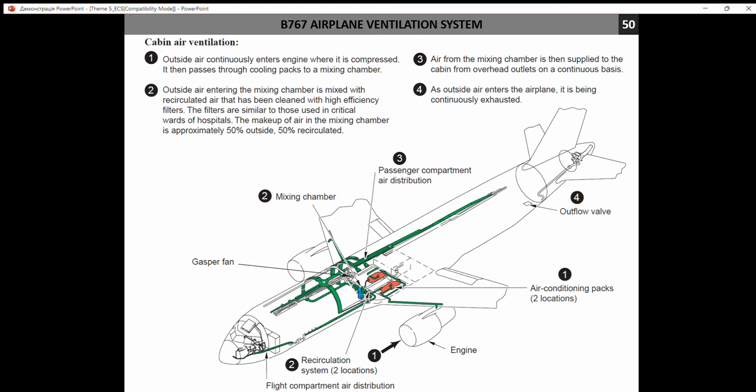And the idea of this system is to supply fresh air. As we said before, 0.28 cubic meter per minute must be supplied for each occupant on board. And if you have 100 occupants, you will multiply it by this value and obtain 28 cubic meters.